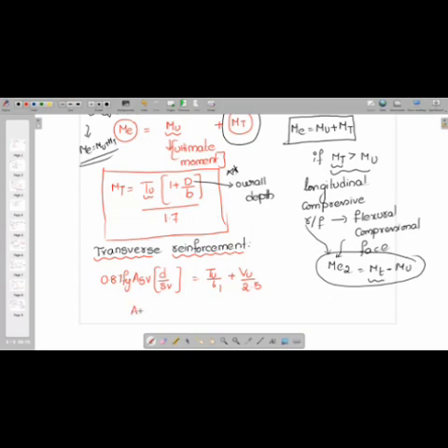And you can also remember Asv is equal to (tau v minus tau c) into b Sv into 0.87 Fy. So in both the cases, you will find Asv, and whichever is more, you will take as your transverse reinforcement. Now immediately your friends will ask me, sir, have you written this? Can I move on to the next slide? We'll solve one problem among this.